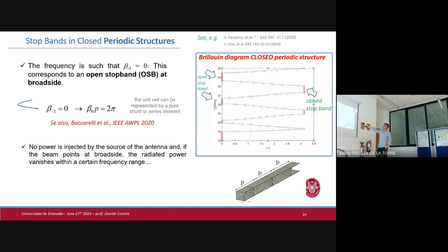And using this loading, you can look at this: the propagation constant multiplied by the period, because this is a convention also in physics. If you follow the frequencies on the vertical axis, you have a spectral region where you do not propagate, a spectral region where you propagate, then you do not, you propagate, you do not, and you go on. You generate a filter. This is a simple exercise. These are stop bands. This one is a closed stop band where beta times the period is pi. This one is an open stop band. Don't get confused, they are the same thing.